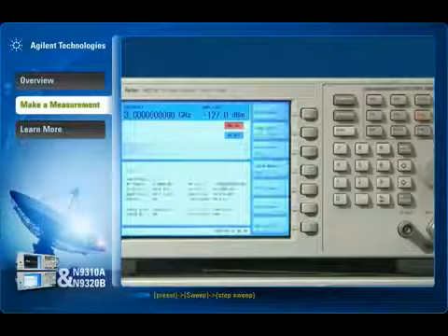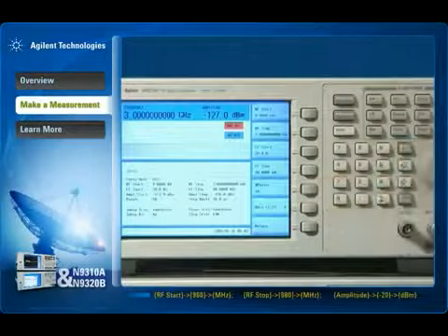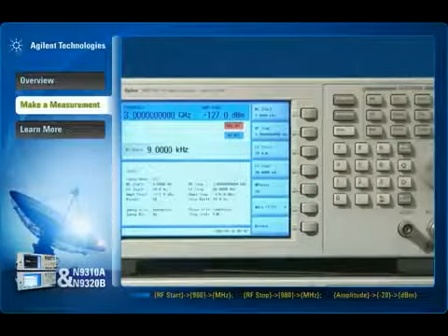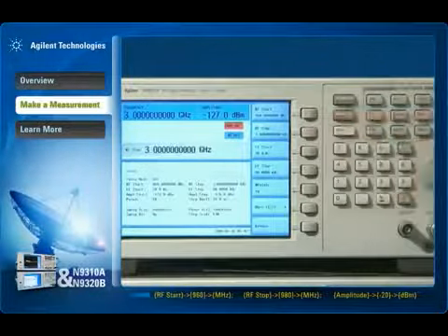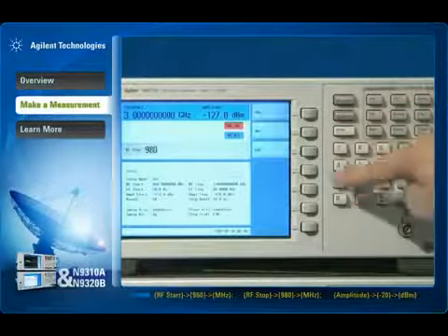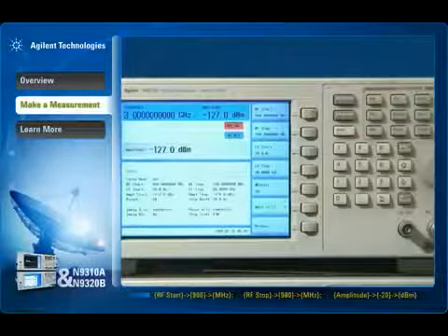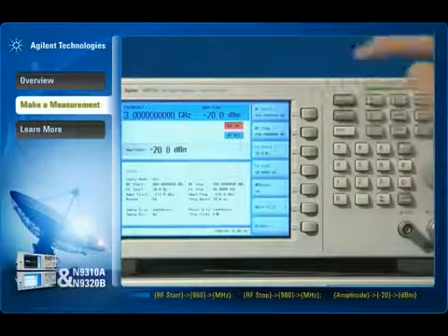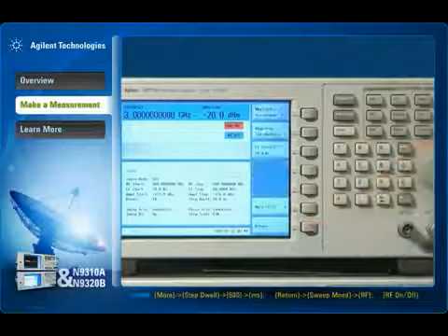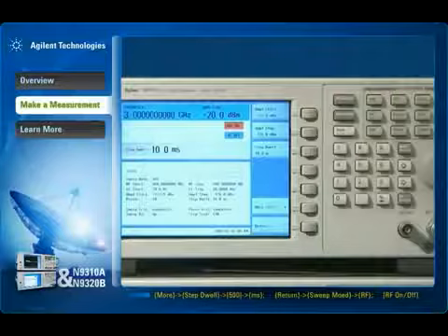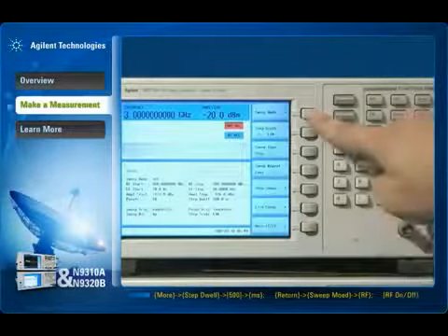First, enter the sweep submenu. Then, set the start and stop frequency, and sweep output amplitude. Finally, set the dwell time at each point and activate the RF output.